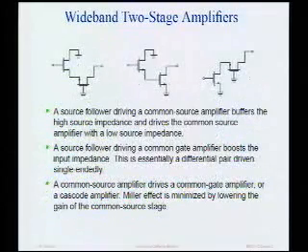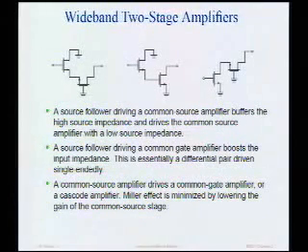Now, one way to fix these amplifiers is simply to go to 2 stages. And 2-stage amplifiers are very convenient, especially for integrated circuits, because transistors are really free. They're tiny. They take up very little area. So if you had to choose between a single-stage amplifier and a 2-stage amplifier, and area were a concern, it basically would not be a concern, because transistors are so small in modern technologies. So we try to use transistors, more transistors, to improve the performance of, let's say, amplifiers. Now here I have the first popular wideband 2-stage amplifier.